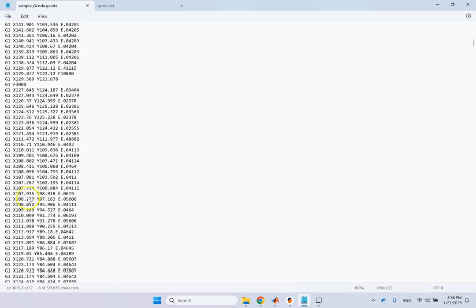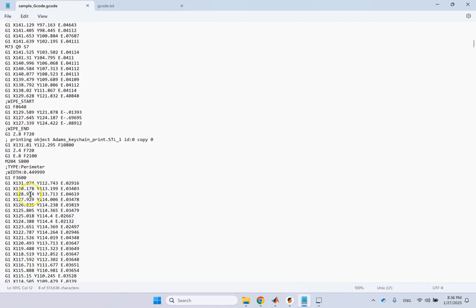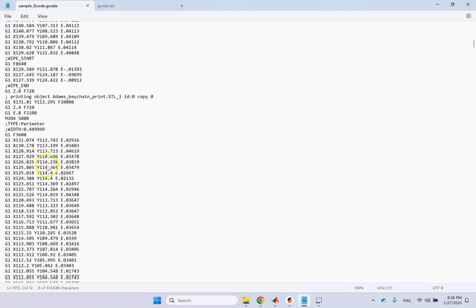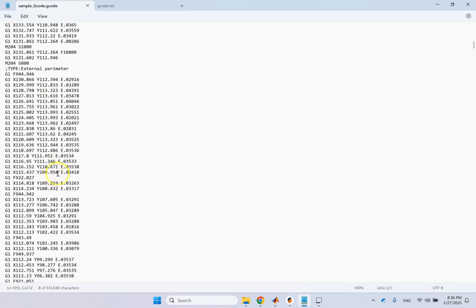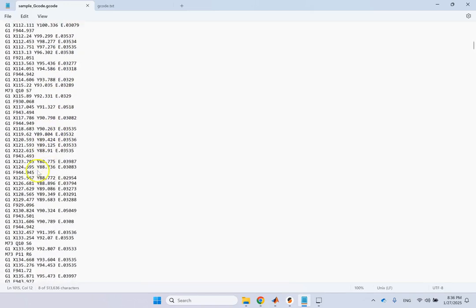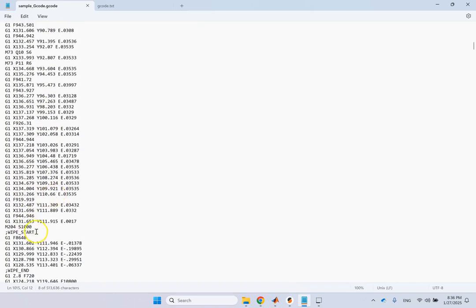Then once this is done, it jumps to Z of 0.6, and it keeps basically repeating, right? So it just does all of the motion for one Z layer. That's why we call it 2.5 axis. So this is all you need to know. Read these G lines, X, Y, see what Z value you had, and keep that.